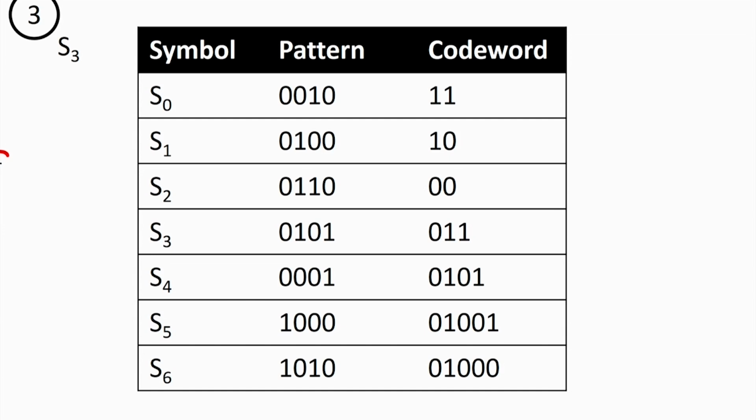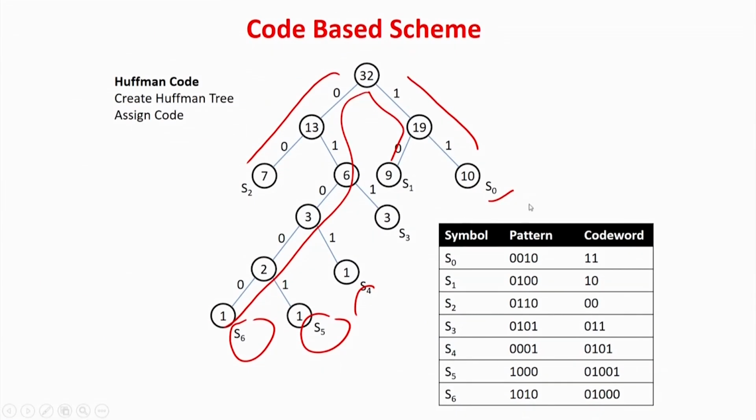So depending on requirement, patterns will be sent to your chip, and the same lines will send to the other chip for the other vendor, but they will be multiplexed. So in this you can see that we have more number of patterns, meaning if you are using all of these, everywhere you will be multiplying by 4. But here, these are occurring more number of times, so only 2 pins are required. So that way we basically optimize.